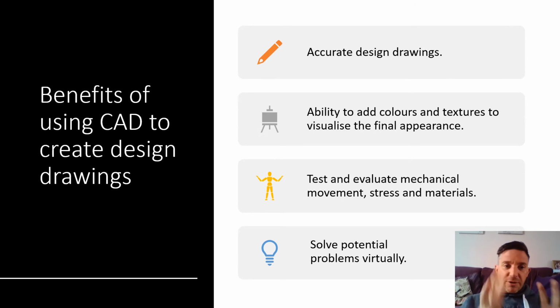So probably for an early stage of design, we're going to look at doing some hand drawings, some conceptual drawings, and then maybe as we progress further through it, as we're getting a design that's more fixed in what we want and its size and its texture and the way that different parts are going to move together, creating some CAD drawings can be more beneficial.